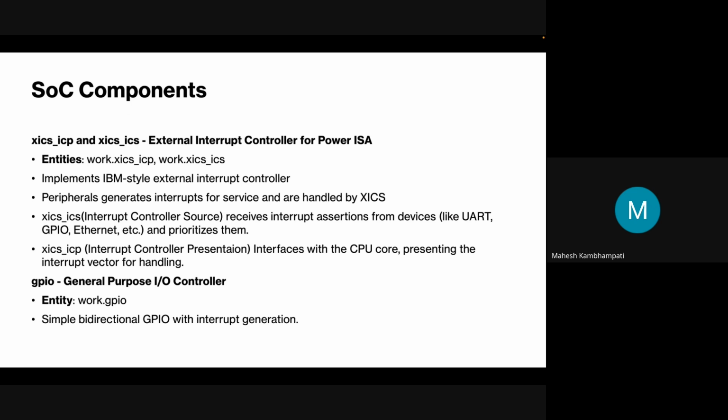So how this works is, since it is memory mapped IO, peripherals are generally assigned an address in the memory. A specific address is reserved for a specific peripheral. If I read or write to the address, I can control the peripheral. There are usually two different mechanisms in microcontrollers, which are polling and interrupts. These are the two main things. Polling is where the processor needs to continuously check if any peripheral needs service, and it needs to monitor it 24/7. So that is the mechanism.